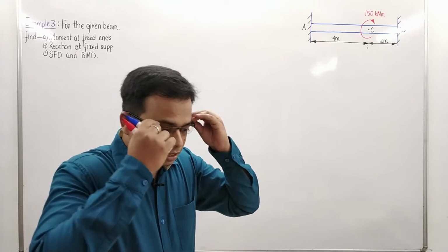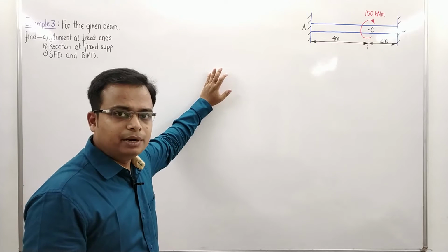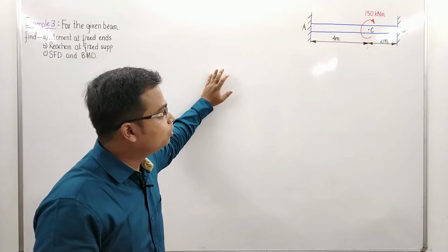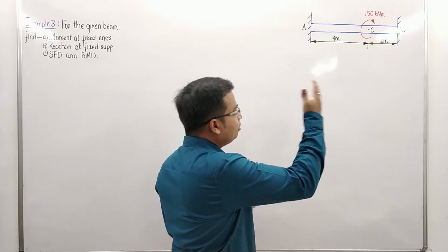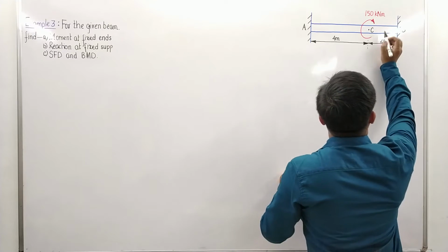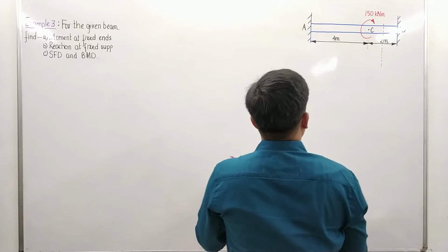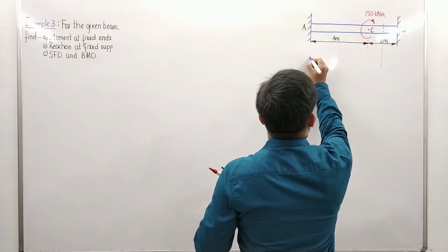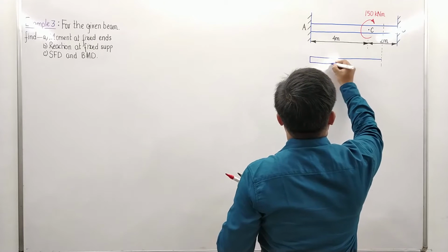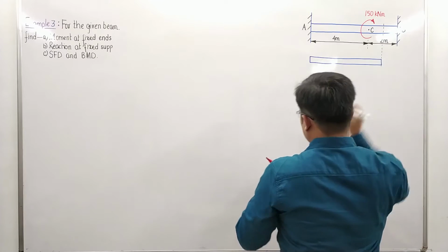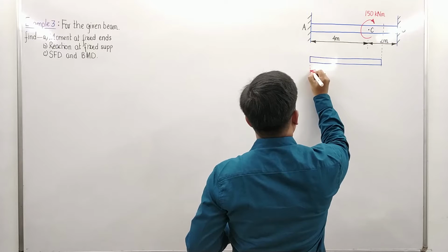Let's start. Okay. So the first thing in any problem based on fixed beam is to take the moment at a section of the beam. So what we'll do is we'll take the section from the left hand side, in such a manner that everything will be covered up. So it's going to be something like this. Do watch. We are going to take a section over here like this. Now let me make the portion of the beam towards this side, and it's something like this. Done.